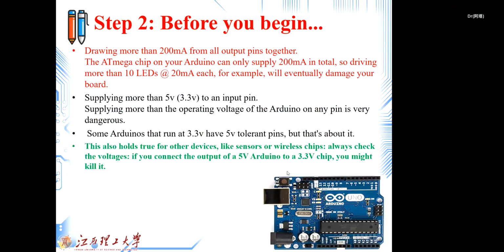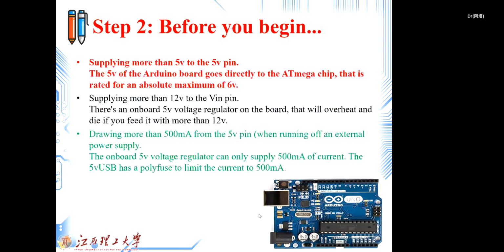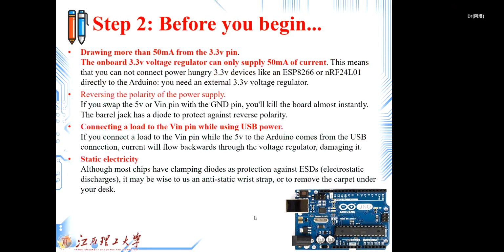Then for your application, the safer side for your stage is using the USB. If you want to use another input for your board, use a 9-volt battery, or an adapter or power supply which gives 9 volts.